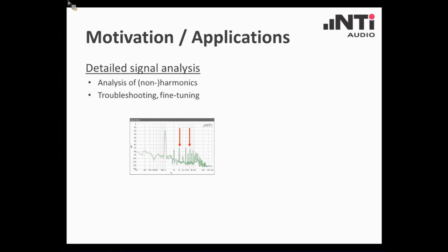FFT is a very powerful, a very helpful tool for analyzing the details of an audio signal, for instance. Let's say you have an audio signal, a distorted signal where you measure a certain THD that is out of range. You may like to know what is the root cause of this distortion. So a look at the FFT, at the spectrum of the signal, will allow you to identify odd harmonics, even harmonics, non-harmonic distortions, all that stuff that may be the reason for the problem.